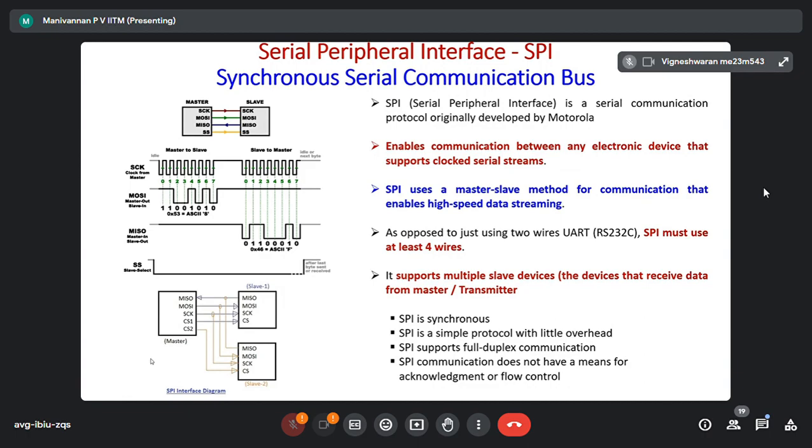Generally, when you want to open the computer, what do they say? First, switch off the power. While the computer is on, inside you have the hard disk, no? You can open your CPU if you know, there are memory chips, correct? SIMs, all those things. You should not remove any of the ICs inside your computer when power is on. Not only will you get shocked, if you remove it, there are chances that the IC, the circuit can fail. Most devices are not hot swappable. Understood, sir. Switch off the power, then only physically remove the RAM. Yes. Okay.